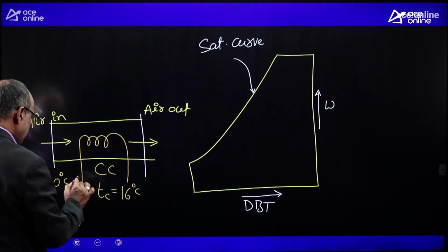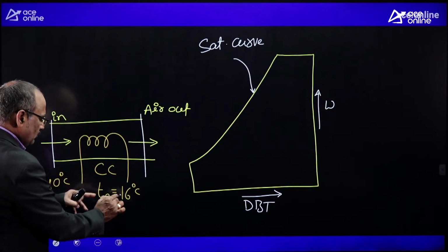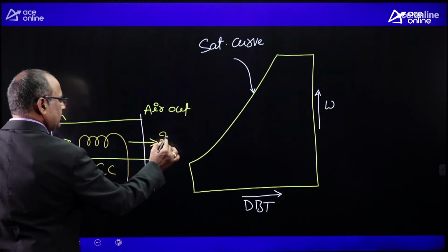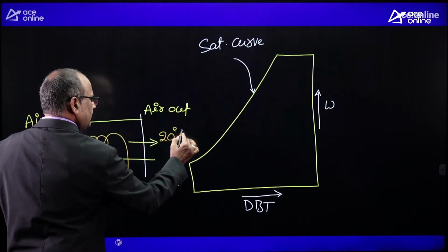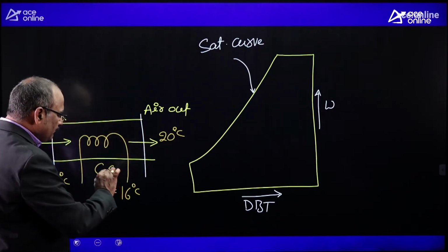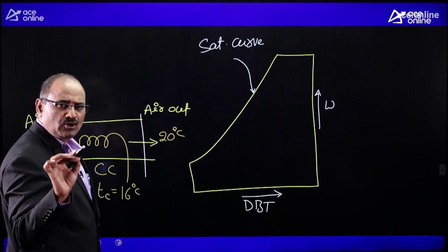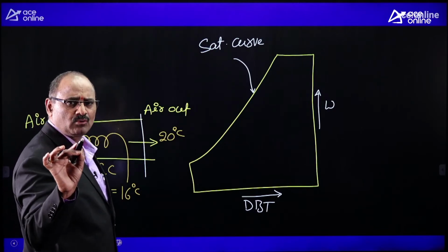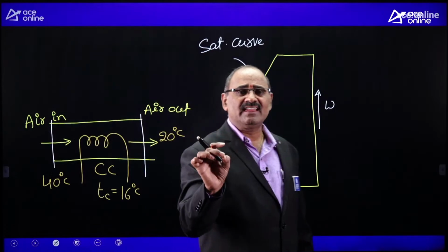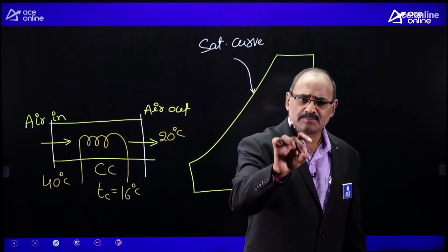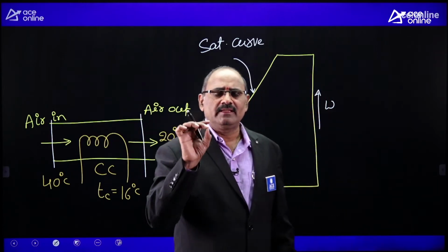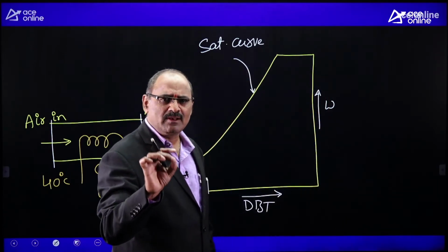centigrade. By the time the hot air is flowing over the cooling coil, its temperature may be dropping from 40 degrees centigrade to some 20 degrees centigrade. That kind of air cooling mechanism without change in specific humidity is called sensible cooling. Once again, the method of decreasing the dry bulb temperature of atmospheric air at constant specific humidity is called sensible